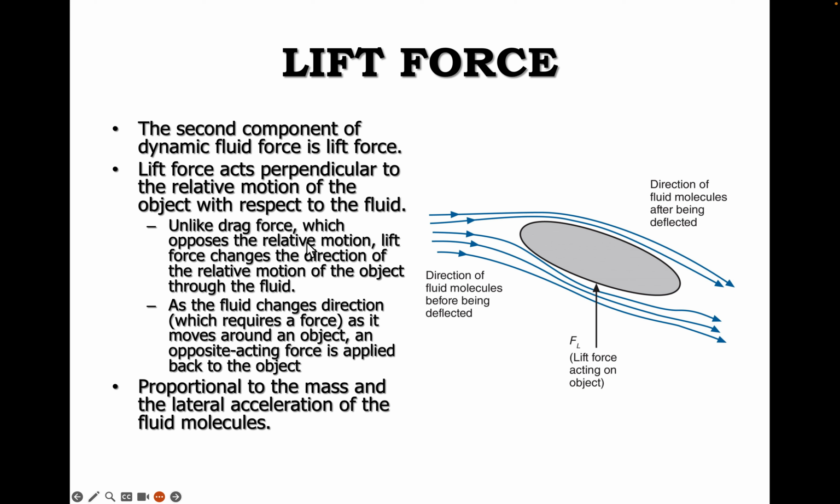Okay? Now, unlike with drag force, which goes in the opposite direction of the relative motion, lift force changes the direction of the relative motion of the object through the fluid. Okay? Example here, if this object was being thrown or was moving to the left here, the lift force will help also propel this object up. Okay? Now, as the fluid changes direction as it moves through an object, there's an opposite acting force applied back to the particular object. Okay? Lift force is proportional to the mass and the lateral acceleration of the particular fluid objects or fluid molecules.